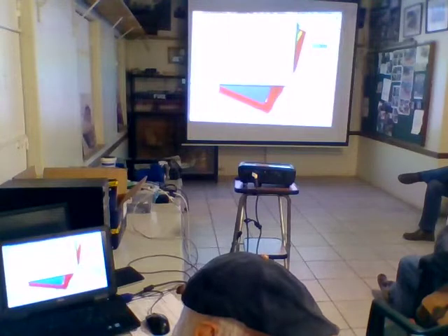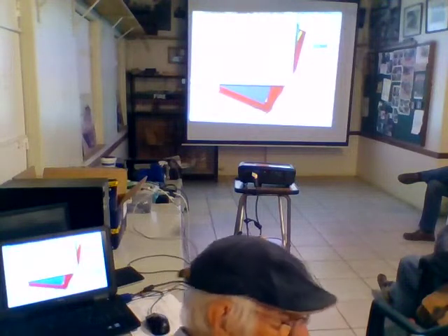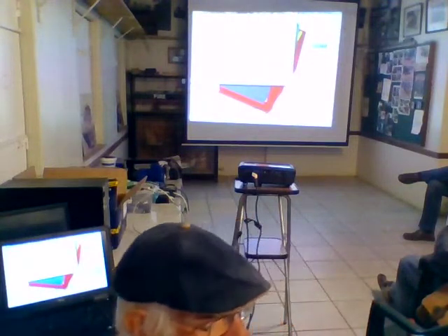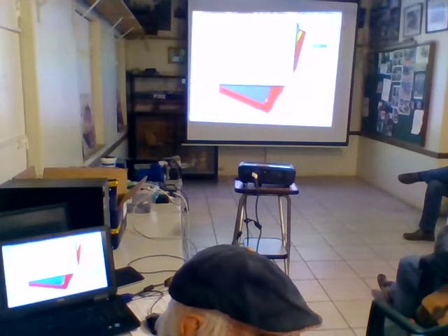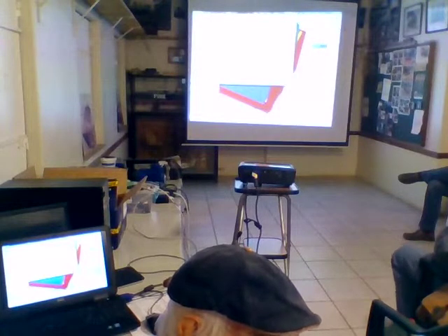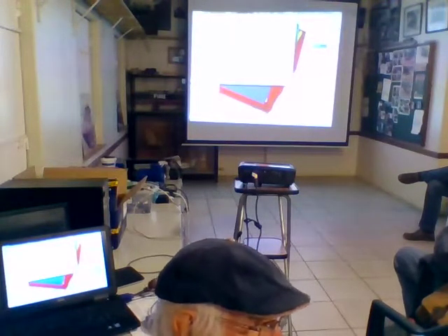So what I've learned is, the more solid and stronger your machine is, the better. Otherwise, at certain speeds, it's going to start making a noise, and it's not going to cut smooth. Not because of tool deflection, but because it picks up a harmonic at a certain rate.